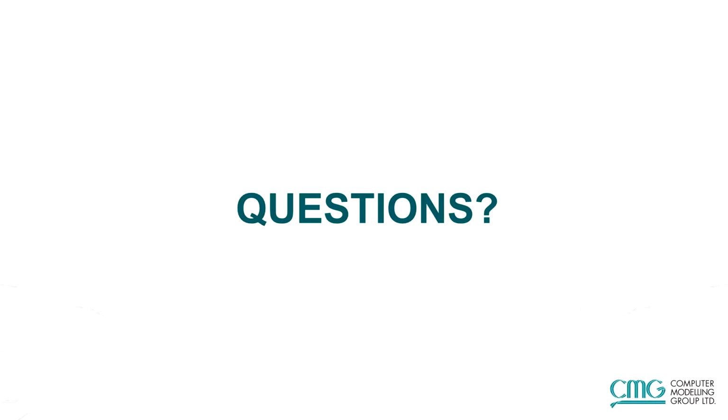The next question I'd like to take is from Charles Hager, and he'd like to know, are there any special handling needs for a salt formation? As long as you can define the properties of the salt properly, you don't have to have any other special handling needs. So you just have to make sure that all the properties in terms of Young's modulus, Poisson's ratio, and so on are defined correctly, and you are using the correct constitutive models. I don't think you can use the general Mohr-Coulomb model there.